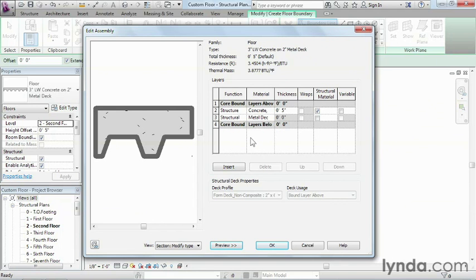Now, this happens to be each layer of material that's going to be associated, in this case, with this floor. By the way, if you ever have this material, metal deck, selected, it'll automatically assume that this little bump structure here, which happens to be the shape of the metal deck when it's put into place, exists, and it'll automatically try to put that in your floor.